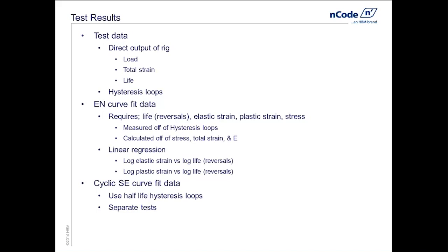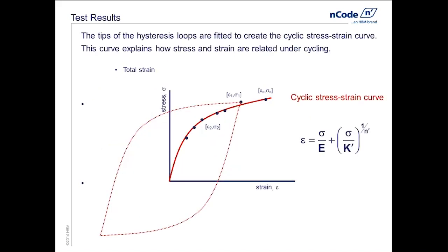So we could either utilize the fatigue tests data to do the regression, or we can go off and do separate tests. In our lab, we tend to use the fatigue tests. However, I have had customers that feel that they can have more flexibility in running separate tests to get the stress-strain behavior. If we're using the fatigue test to generate this curve, we're going to have a whole family of hysteresis curves, each one of these at a different strain level. And so at the lower strains, there's smaller hysteresis curves, and as we have higher strains, they become larger. And what we do is we pick the upper corner of the hysteresis curve, and that point is used as a stress-strain value on my stress-strain curve. So what you're looking at here, these blue dots, are basically this upper vertex of the hysteresis loop for different load levels.